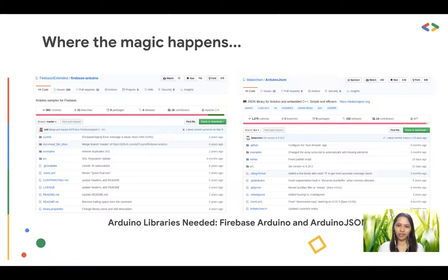and embedded C++. Because in embedded systems, when you receive data from sensors or other electrical components, it's usually in a type that is not human readable. It's a series of characters that we cannot understand, so we have to convert this data in order to make sense of what we are receiving. So we're using Arduino JSON for that, to convert it to a string and later on convert it into JSON so that we can send it to our cloud server and store it in a database.